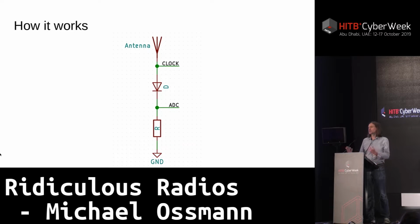And then the analog to digital converter measures the signal that's passed through the diode, through our mixer here. I call it a mixer because what it does is combine the clock signal coming from the microcontroller with the signal from the antenna, and it produces from those two different frequencies additional frequencies. They're called mixing products, and one of those is the difference between those frequencies.